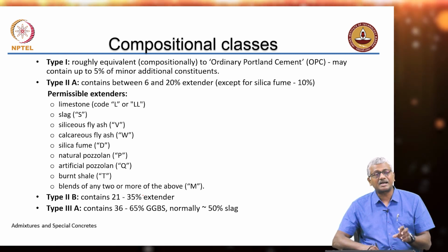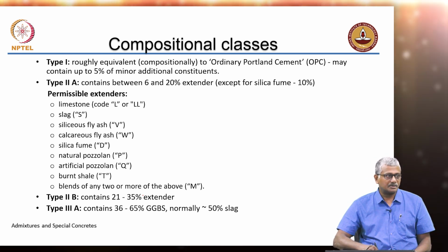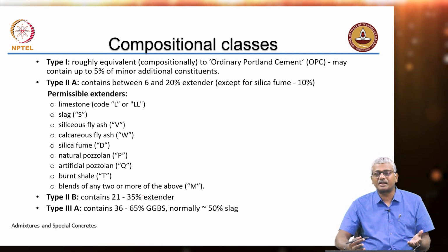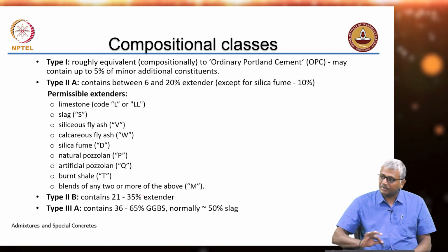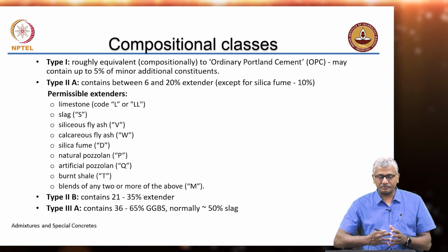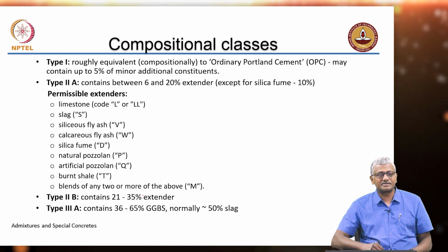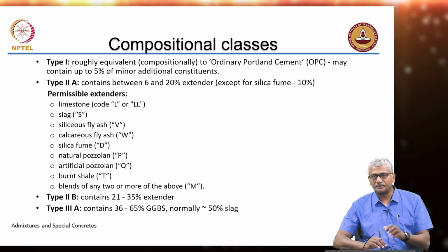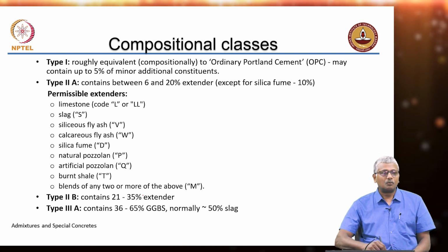In India, the understanding of the cement is not as good with the civil engineers that are available on site. We are familiar with ordinary Portland cement, but beyond that, even admixtures, mineral admixtures sometimes are out of reach of many people. So, we need to be careful when we classify cement in too many categories. The problem is then that we have difficulty deciding which to use when. But in Europe, the degree of understanding with these special cements is very good, and they have very well trained people, concrete technologists who can actually understand what each of these cement is.